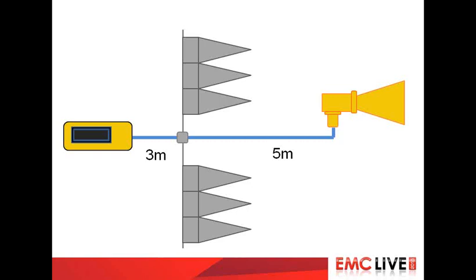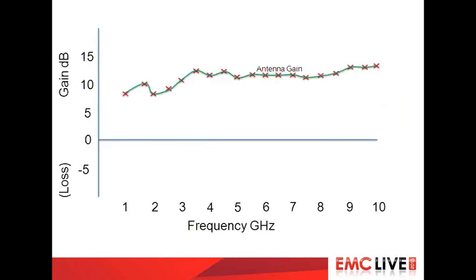Those are reasonable numbers. So I alerted you earlier that, particularly for me, and I recommend for you, is to make things visual so you can see what is happening with the system overall, all the way from 1 to 10 gigahertz. And this is particularly important because you want to be looking for any suck-outs whereby misfortune, a dipping gain in the antenna happens to coincide with a high frequency cable loss, and by visualizing it, you can see immediately if you're going to hit a problem early on.